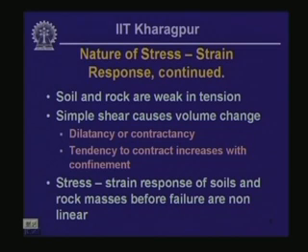Normally what you would expect is that when you apply shear stress, then there is no volume change, whereas when you apply normal stress, then only there is a volume change. But in case of granular material, we tend to see the feature of dilatancy, where when we apply shear stress, then the volume also tends to change. We are going to look at the details of this type of behavior in the next little bit.